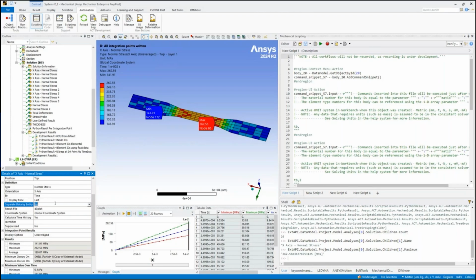Okay, we could do it if we used ACP, so the Ansys Composites pre-post processor, then we could have done some more detailed investigations into the per ply response. But if you haven't got access to ACP, or you need to just use Ansys Mechanical without ACP, or you just need to get access to those individual directional stresses within each of the plies, then I can actually use Python to do that. So I can start adding in functionality to use Python to interrogate the model and to bring in results from an external D3 plot file. And the mechanism by which I do that is to do what's called a Python results type.